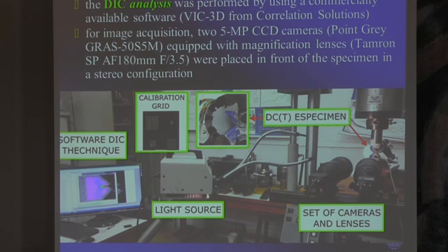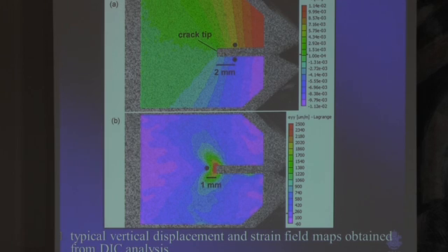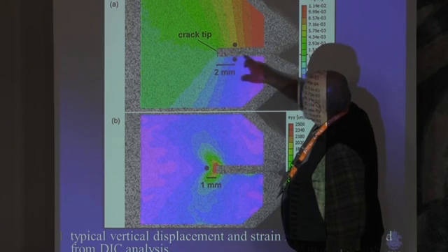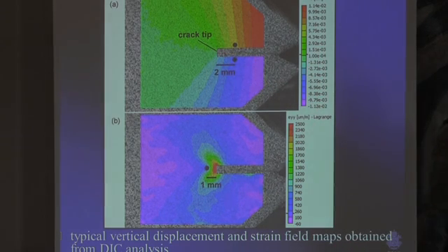Showing exactly the same technique we used in this field. We did the very same exercises in order to calibrate the system. And we also used the strain field ahead of the crack tip to measure the opening load. We did avoid, though, the very near part around the crack tip to avoid the plasticity constraints, just to use the Williams field and things like that with confidence.